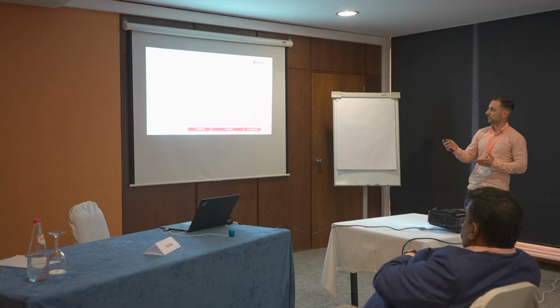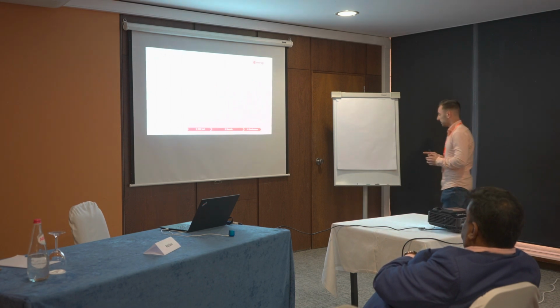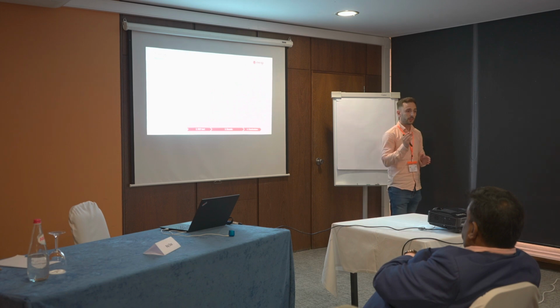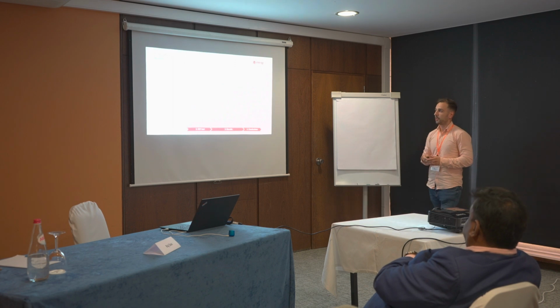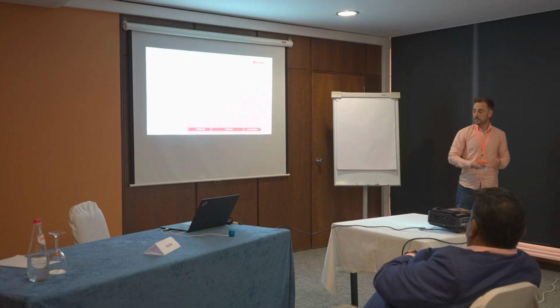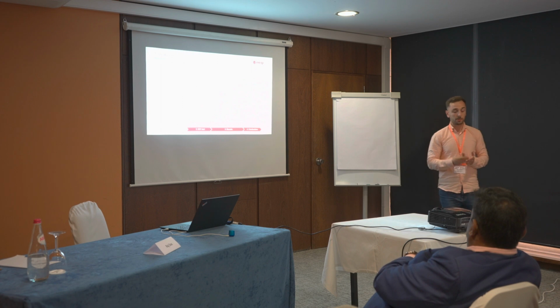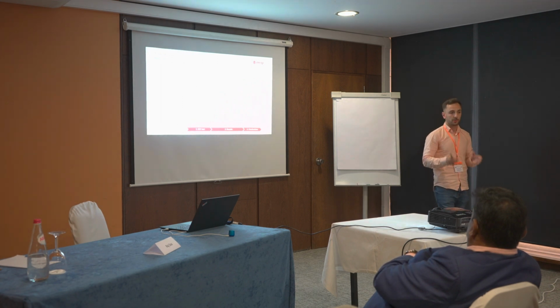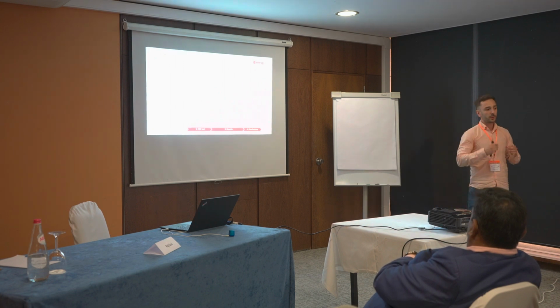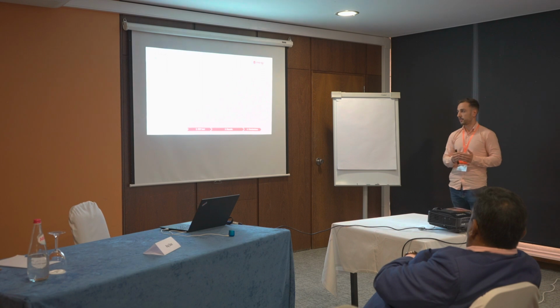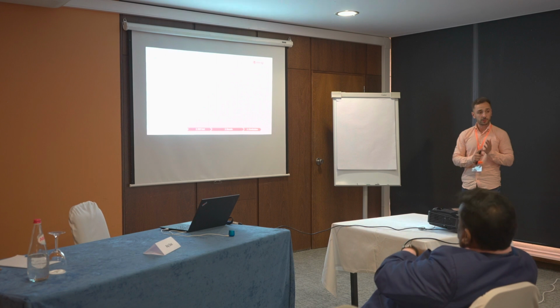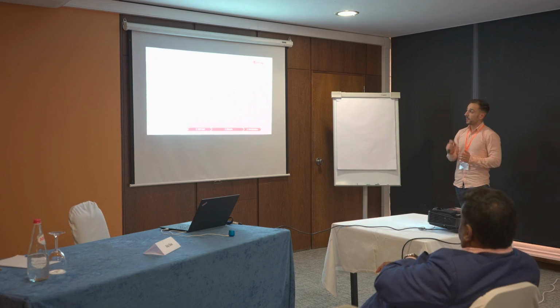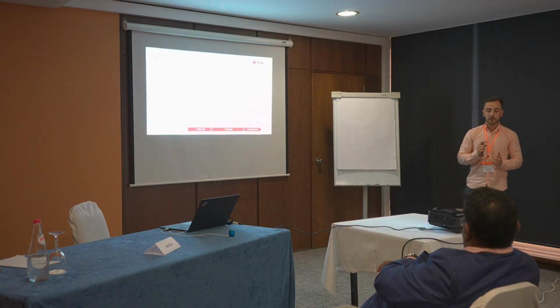But there is one regulation that is applied to a truck with a separated cab. This is Regulation 29, and it certifies the vehicle in case of frontal collision, but it is applied just to trucks with separated cabs. As this is an investigation project, we are going to adapt this regulation to our case. We are employing several experimental methods to monitor the structure, and we are going to employ numerical methods as well.